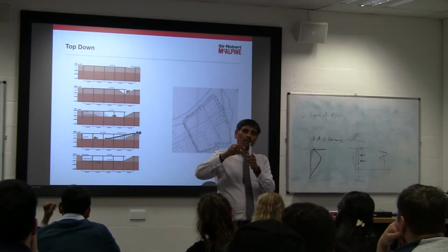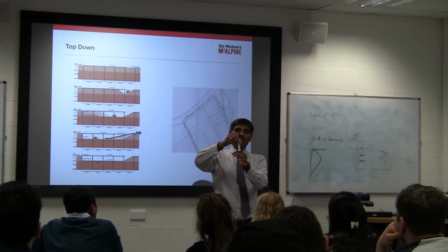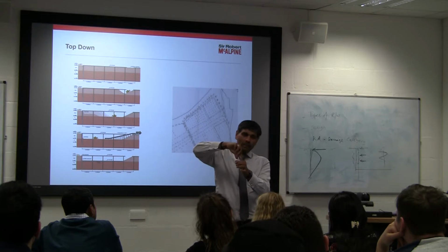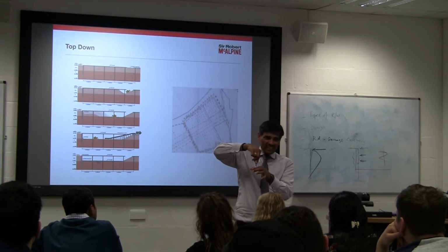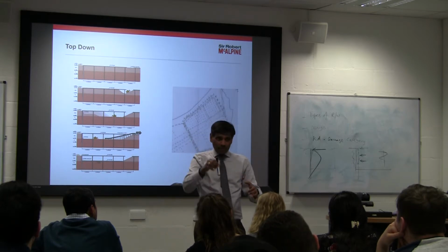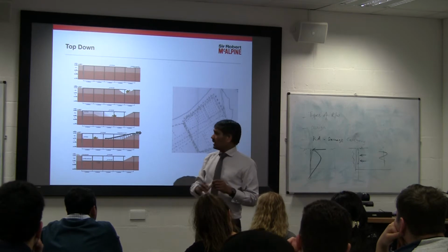Now when you drop it, this will have a template all around it. Because it's the casing, people can control the tilt of this, and it's got a plate, 2 levels of plates here. That plate covers the perimeter of the casing. So when you drop it, it cannot go anywhere. So it's actually got 2 levels of template where people can control the tilt of it, and there is a bit of a tolerance here and there, 10-15 millimeters.